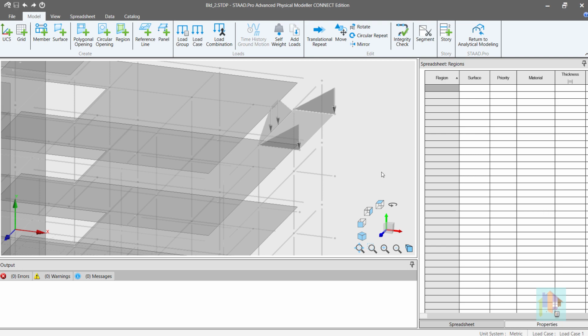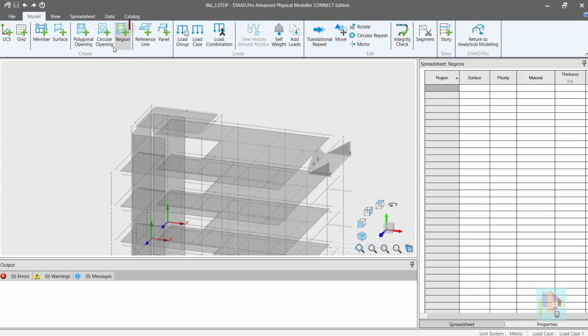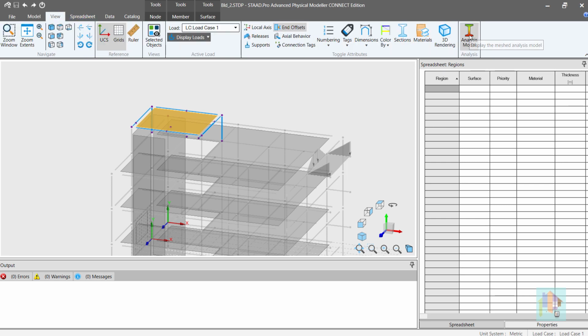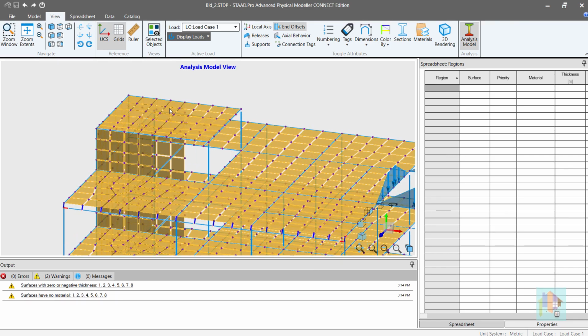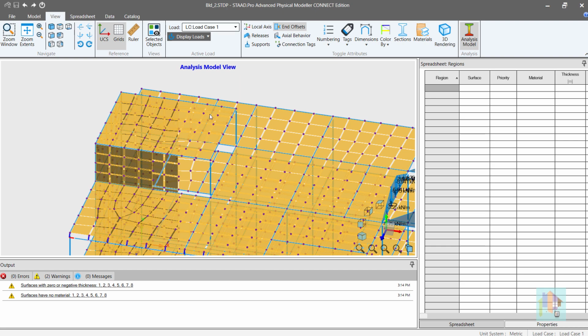where you want to apply the floor load. There is another option available to apply load on a structure, the reference line. The function is similar to panel. This is not a structural element. Rather, this is just a reference along which you can add any line load. For example, an internal wall is not modeled and you want to apply the wall load directly on the slab. In such a case, you can use this feature.